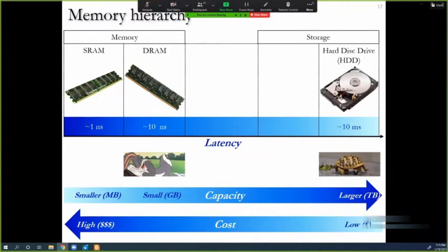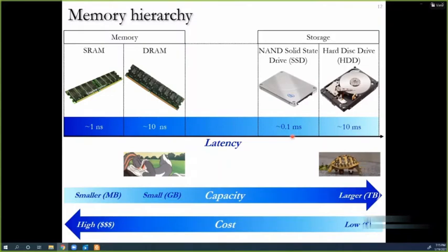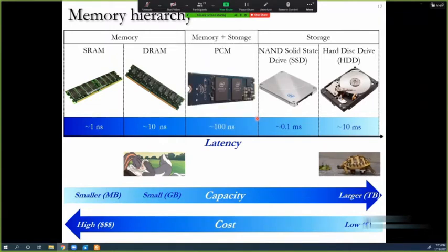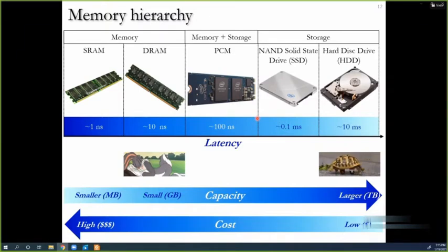So, this large gap can be bridged with the solid state drive, which is composed of the NAND flash technology. But here you may notice that the write latency is not super high for this NAND flash technology or these SSD devices either. We can only go up to a maximum of 2 orders of magnitude higher in the write latency, but there would still be a large gap between the storage and the memory devices, and the problem is still not solved. Hence, nowadays, many emerging technologies are evolving, including the phase change memory that has properties in the middle of the memory and storage devices.